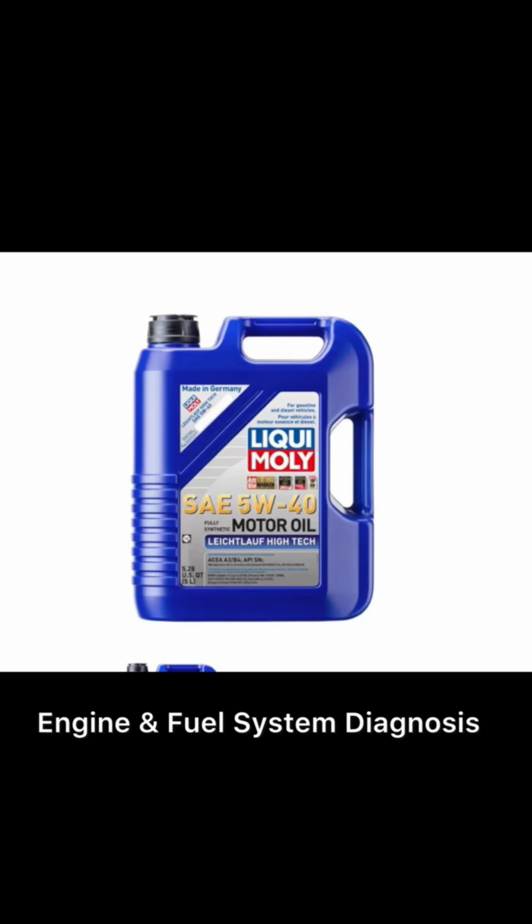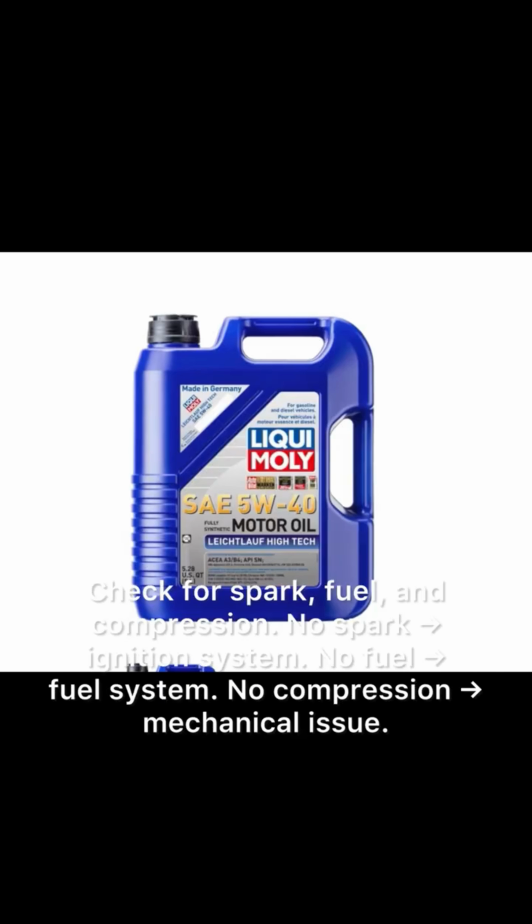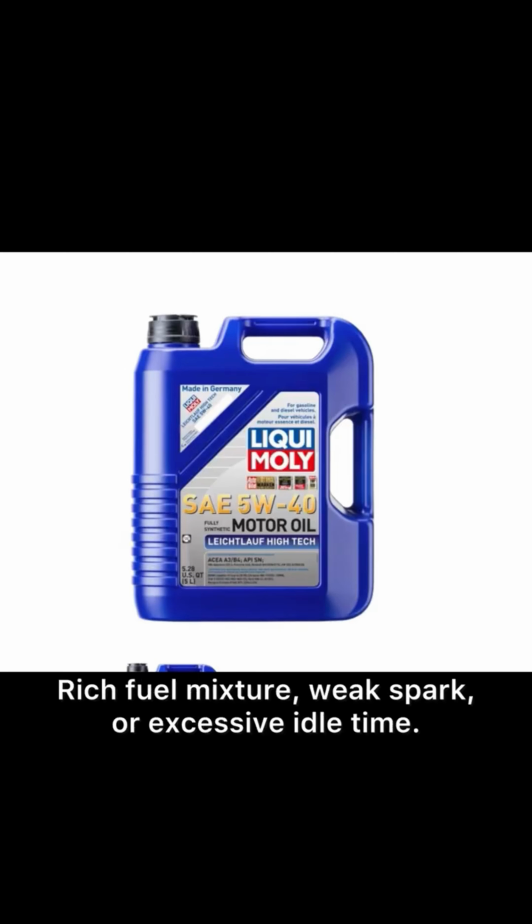Engine and fuel system diagnosis. Engine cranks but won't start. What's your first check? Check for spark, fuel and compression. No spark: ignition system. No fuel: fuel system. No compression: mechanical issue. What does a black, sooty spark plug indicate? Rich fuel mixture, weak spark, or excessive idle time.